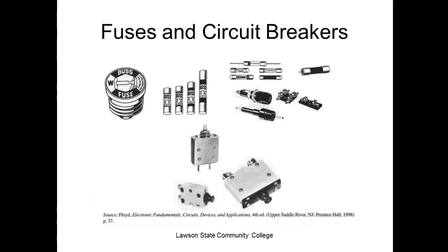What's the advantage of a fuse? Cheaper. By the way, the fuse is made out of a metal that melts at a fairly low temperature. And we already know that that fuse has a small R. Very small. In fact, the bigger the fuse is, the less the R. Your small fuses, like your 10 milliamp fuses, those guys might have 10, 15 ohms. But you're not putting hardly any current through them, right? You understand that? Your big fuses, like your 15 amp fuses, you measure those and they're going to measure almost 0 ohms. But it's still got ohms.